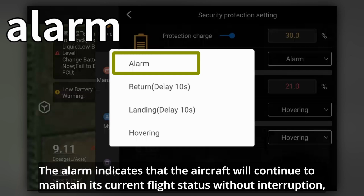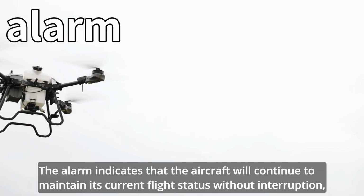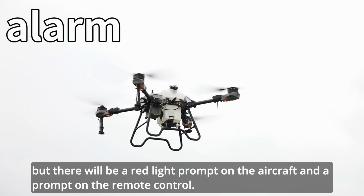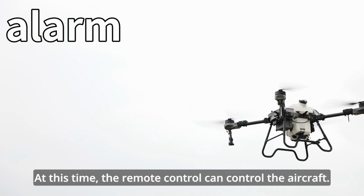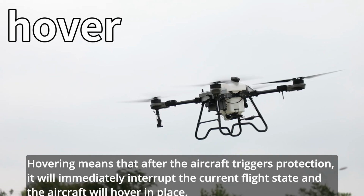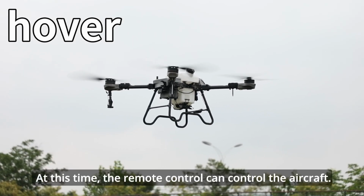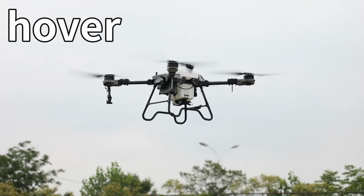The alarm indicates that the aircraft will continue to maintain its current flight status without interruption, but there will be a red light prompt on the aircraft and a prompt on the remote control. At this time, the remote control can control the aircraft. Hovering means that after the aircraft triggers protection, it will immediately interrupt the current flight state and the aircraft will hover in place. At this time, the remote control can control the aircraft.